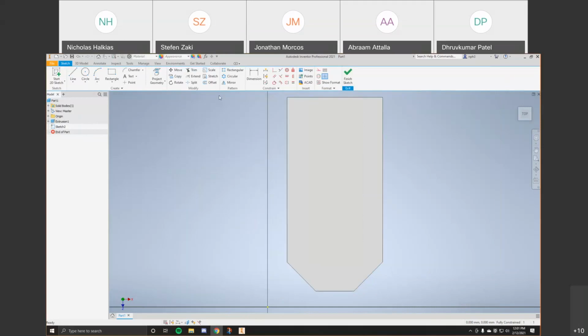So what we want to draw here is this. Again, our rectangle before only went up to 60. So first thing we want to draw is another rectangle that is 18 by 30. We already have this as our drawing plane. We're going to click in the corner here. We want that bottom dimension to be 30. Again, you just type it in and hit tab, and then 18, tab. This creates our rectangle. Enter.